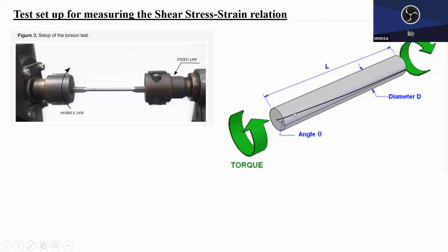To rotate, you apply moment or torque. And you can see one end is going to twist more and more if this end is fixed. But action torque, reaction torque: even though this end is fixed, there's a torque here. Then rotate, rotate. Remember, the shear is the angle change.